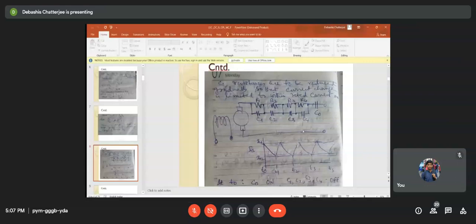So that is what is written here. The resistances are to be reduced gradually so that the current change is limited to within the rated current or the desirable current. I have shown the current graph here. Initially you design it such that it is 150%, and then it reduces to a value IA2, maybe rated current or 80% of rated current, whatever it is for the design.